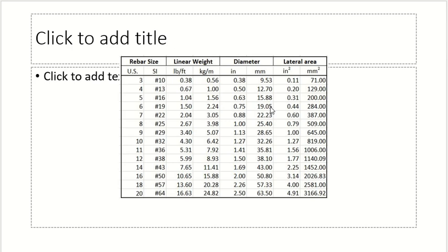Can we do the same for the next, but we change the diameter? Diameter will change, the length will change, that's why the unit weight remains the same. Sir, 7850 number 8, it's given. Yeah, he gave. And the 4, radius 4, because it was 8 diameter, so 4 it is. We are doing it for the stirrups. The stirrup is 8 millimeter dia.